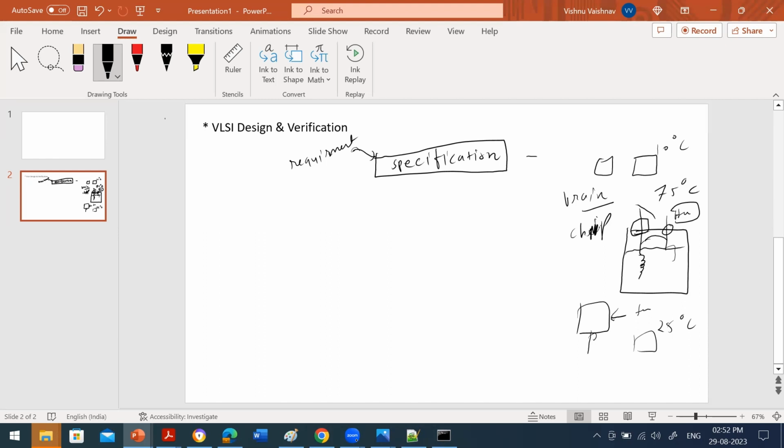It will just send the instructions, like 1 or 0, and that's what controls your heater. As soon as it identifies that the temperature is below 75, it sends the input to the heater to turn on, like a VCC supply or 1. That's how this part would work.